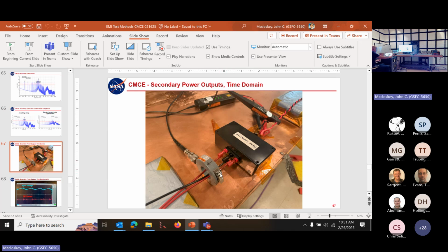So here we'll take some measurements of the common mode on the output. We'll basically just lump these 3 wires together. I'm going to consider this as a cable bundle. That's more meaningful than an individual measurement on each wire anyway. Like in a real configuration, you would probably twist these together anyway.